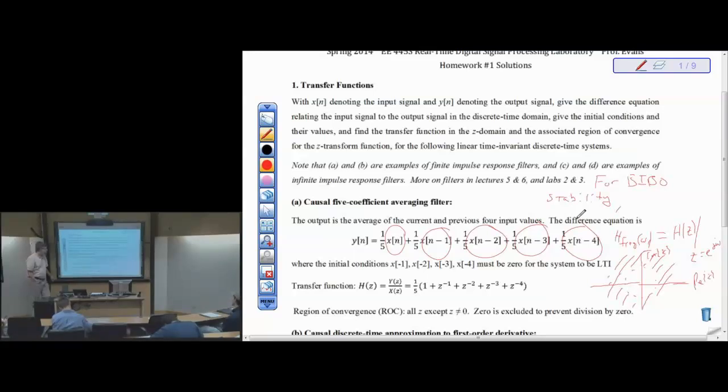And the cutoff frequency, the first null, so we do null to null bandwidth. We'll see this coming up later, so this is just a preview, but the null to null bandwidth is 2 pi over n, where n is the number of coefficients. So for a 2-tap averaging filter, my first null is at pi.